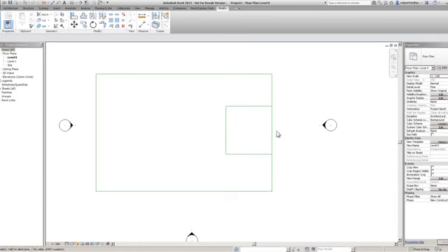As you can see, it's like break at point in AutoCAD. It's just basically split that line into two lines. So what I'm going to do now is go trim extend to corner, pick that line, pick that line, pick that line, pick that line. Done. Nice and easy.